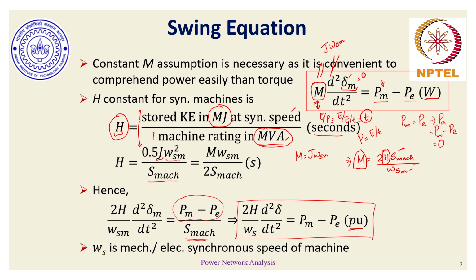But just to highlight the importance of H in terms of different generating resources connected to the power network, from the transient rotor angle stability perspective: if we have resources which are non-rotating in nature, for example solar PV plant, battery energy storage systems, and related static devices, then what is essentially happening from the power network perspective is the following.